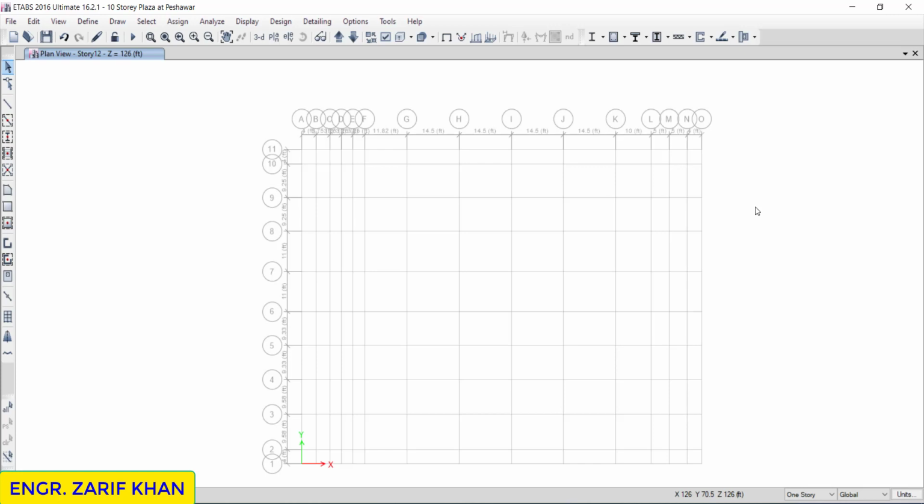If someone wants to design something, he must know and observe all the buildings, to see how I can choose the section. If I choose a section and its formwork is not available in the market, it will be a problem. So the designer must keep in mind to choose a section for which the formwork is available and can easily be provided on the site.